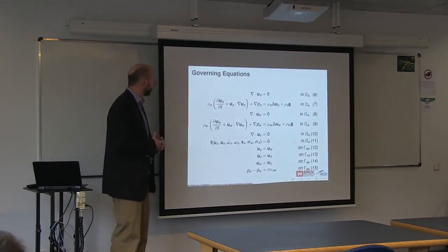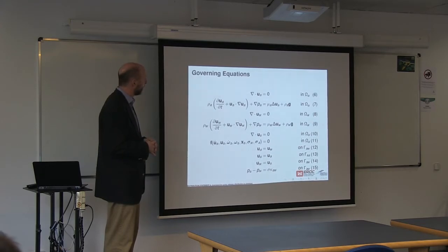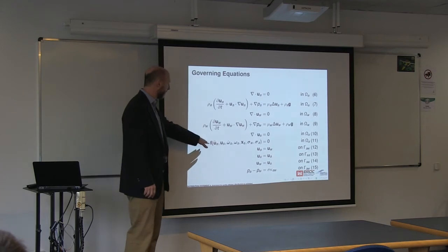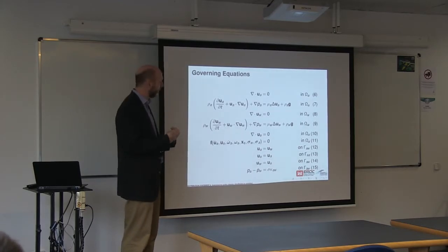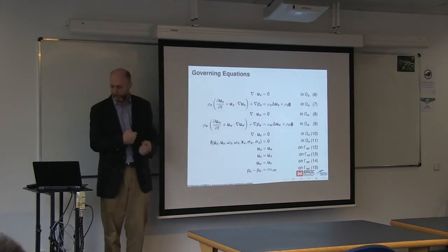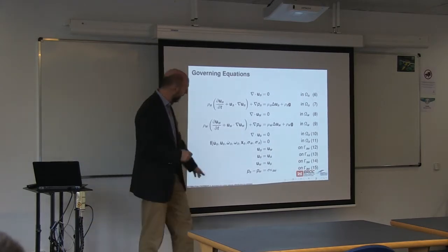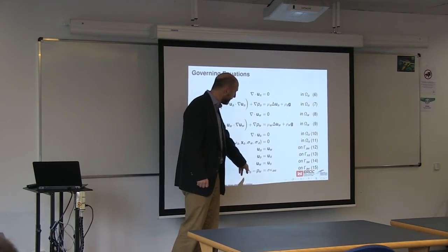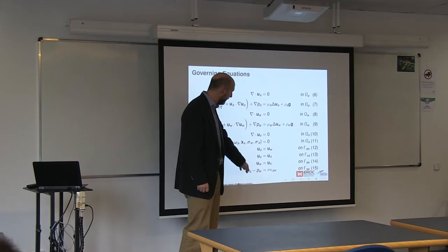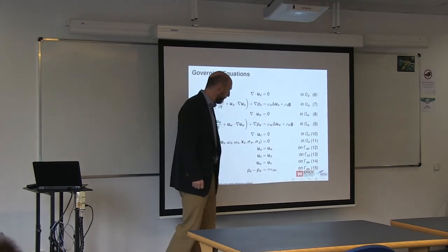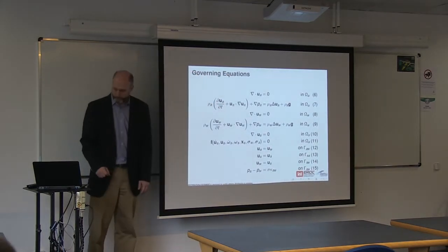So the governing equations for this model, we start with incompressible flow in each phase. And then for the solid phase, we're just going to have 6 degrees of freedom motion, so a system of ODEs for the solid phase particles that includes potentially interaction terms. So we're solving the evolution equation for each particle and then potentially also interaction forces when they collide or roll past each other. We may also include a surface tension jump. So the boundary conditions between the phases would be continuity of the velocity and either continuity of the pressure or a jump in the pressure due to surface tension.